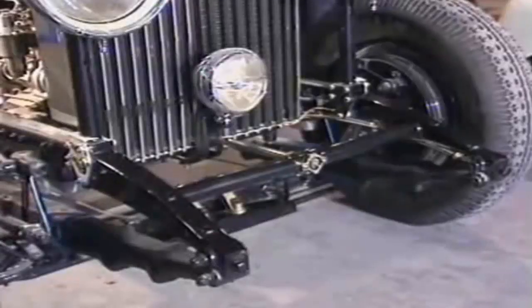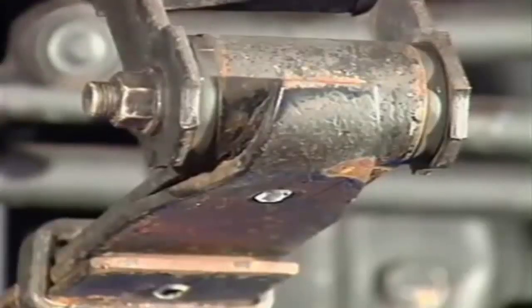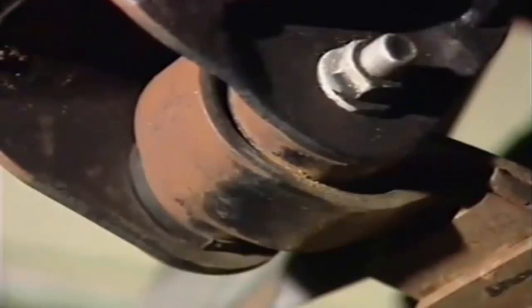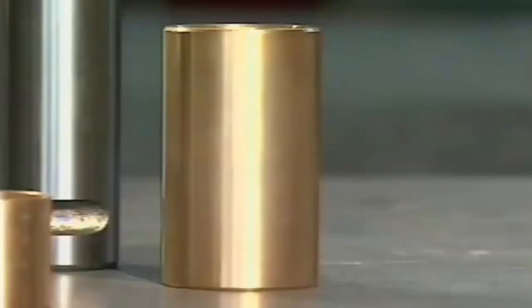Some springs have inserts between the leaves of plastic, nylon or rubber. They act as insulators to reduce noise transfer and friction as the leaves move under load. Some older vehicles completely enclose the leaf springs in grease. The spring eyes are fitted with bushes, usually with a rubber, flexible section. But nylon and urethane bushes are also used, and sometimes bronze for heavy-duty applications.